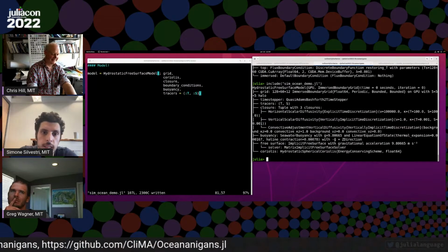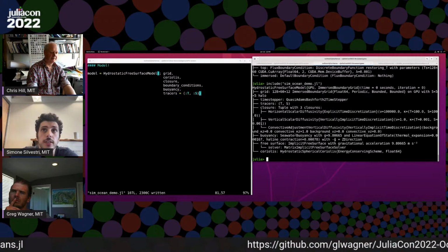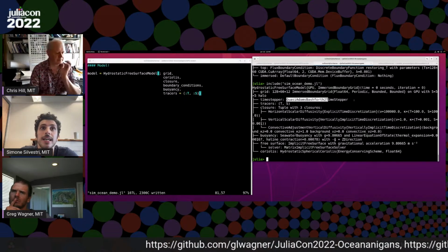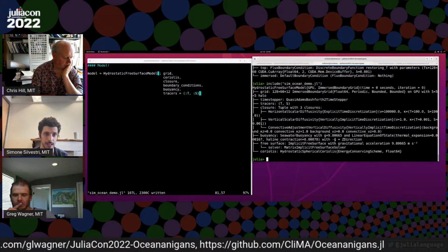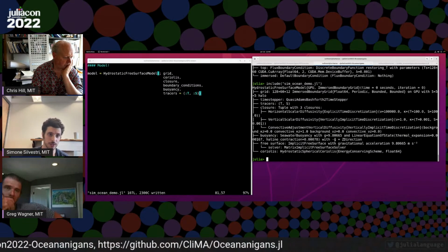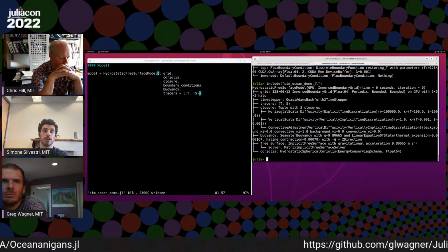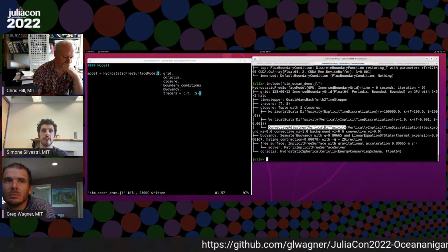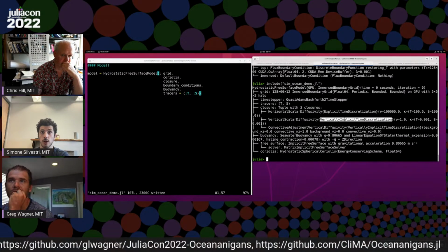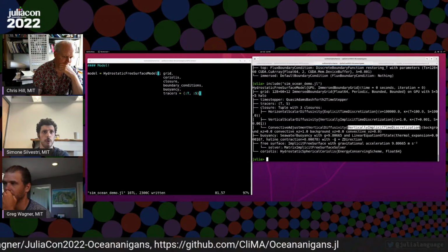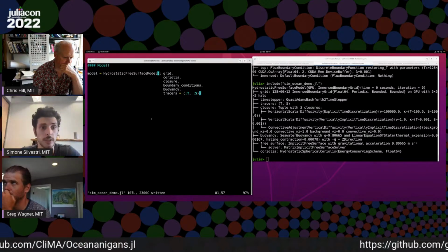Okay, we have it. So this is our model, which runs on a GPU on an immersed boundary grid. It has an Adams-Bashforth time stepper. At the moment, we only implemented that for the hydrostatic free surface model. We cannot use other time steppers. It has temperature and salinity tracers, and these are the 3 closures that we defined. The horizontal one is explicitly stepped, while the vertical ones are implicitly stepped. We have our buoyancy, and we are ready to run this model.